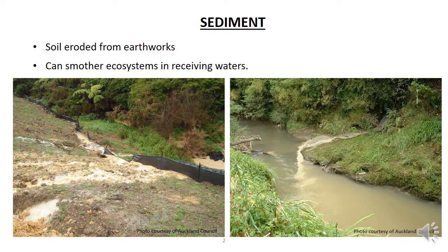When we remove vegetation or other ground covering on a site, we expose the soil to the weather. Raindrops impacting the ground and surface water flow erodes the soil. This eroded soil is called sediment. The sediment is carried by the runoff to streams and other water bodies. The sediment settles in the water bodies. It smothers plants and other marine life and can significantly degrade the whole ecosystem.